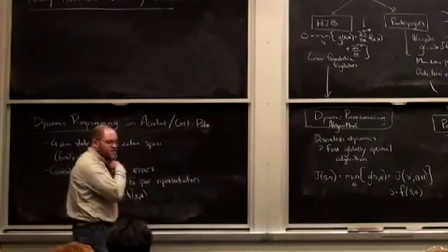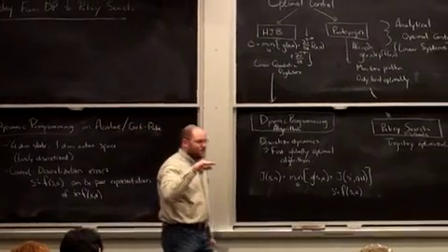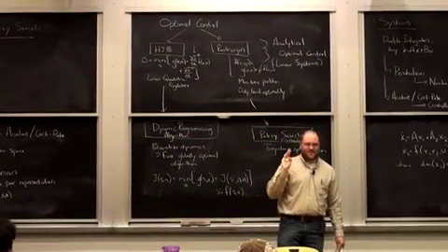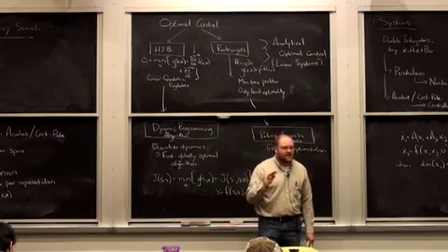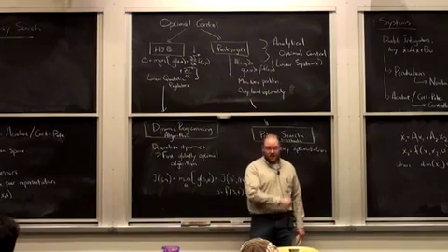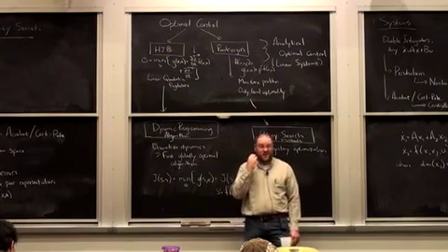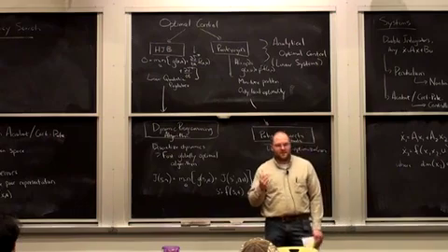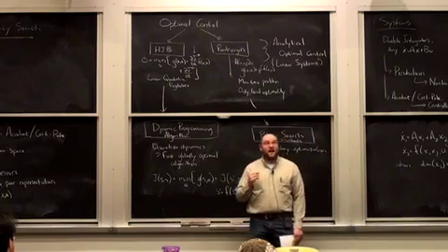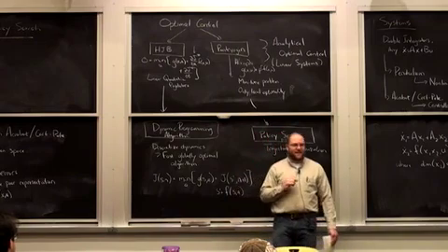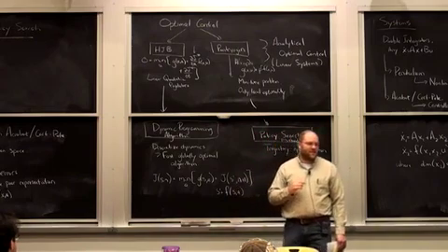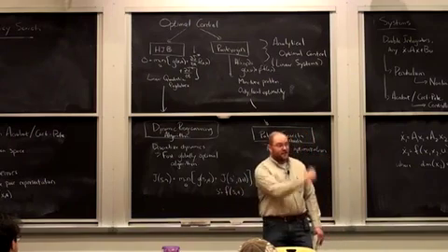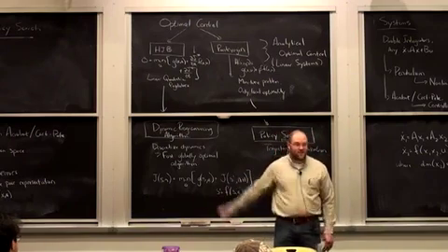Even just making sure that energy is conserved when you put no torque into your system is the basic thing you do to make sure you got your equations of motion right. With the Acrobot, you have to put your integration tolerances up the wazoo to conserve energy. The relative tolerance in the ODE solver in MATLAB had to be something like 10 to the negative 9th to make this thing integrate and look like it had a flat line in energy as it's just swinging around with zero torque.